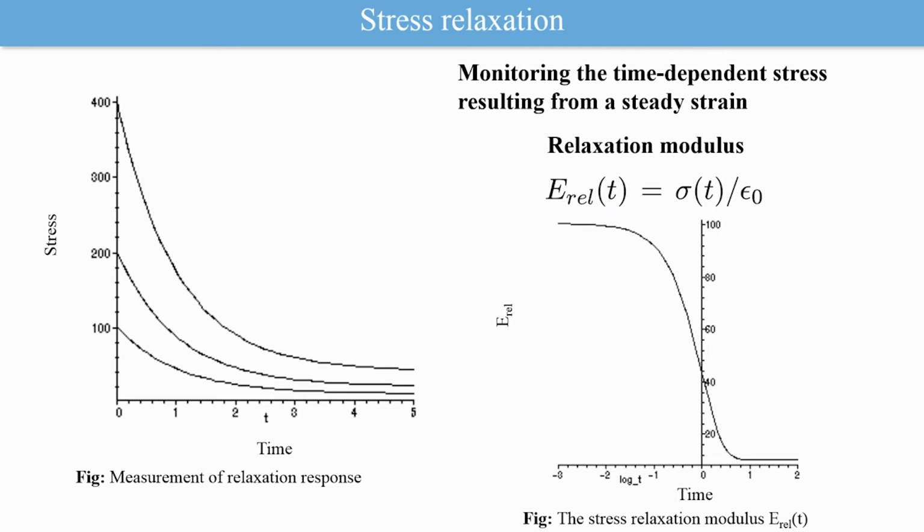And similarly, the vice versa of this is basically you apply different strains. Initially, this was the tissue, you compressed it to say x distance, and in the next case you compressed it to 2x distance, and then to 3x distance. Now, what happens is each different displacement also causes different stress in the materials.